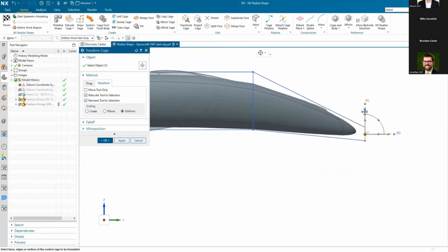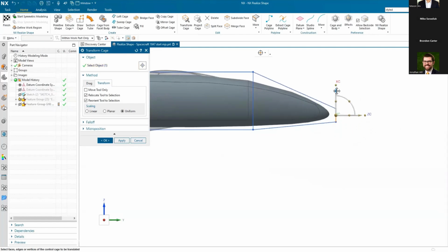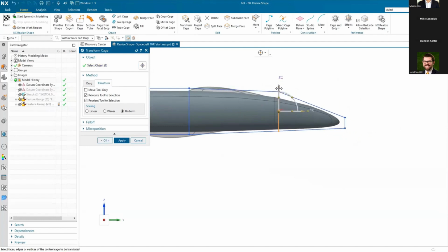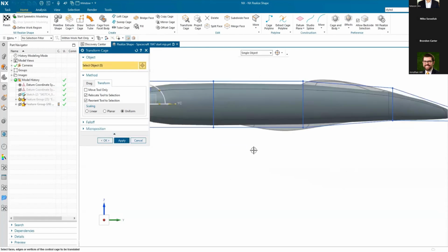And what you'll notice is I'm not starting with a sketch. I'm not lofting anything. We'll get to some of those tools later, but in this case, the realized shape is so powerful in that I don't need to develop any of that. I'm using this cage to drive that. So if I need more detail, I split it up, I divide it up into more sections. As I go and start to drag and push and pull, it's just the speed.